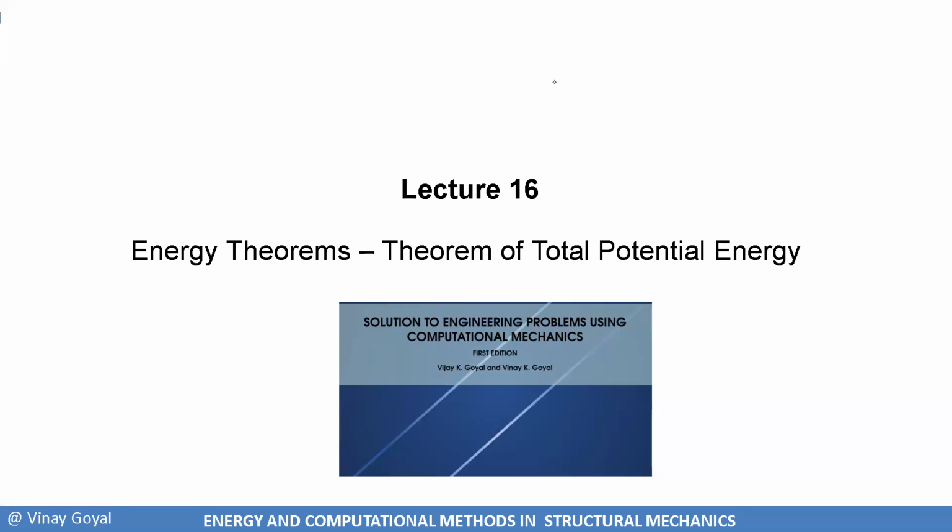So then later on, I stopped talking about those equations. And then I applied the calculus of variations through the principle of virtual work to derive structural theories. And a miracle happened. When I applied the principle of virtual work and demonstrated the internal virtual work done is equal to the external virtual work done, which in my opinion is a miracle, and used calculus of variations, the Euler-Lagrange equations happen to be the very equations I had derived using Newton's second law, or Newton's law in the integral form, which is amazing.